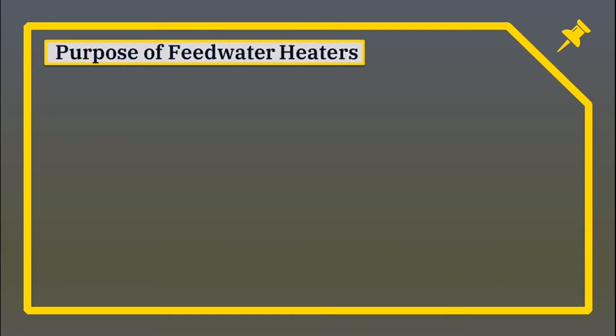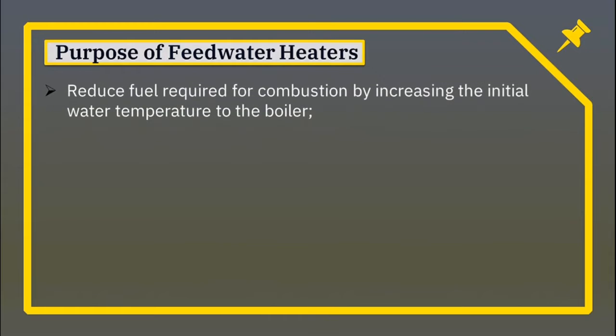Why use a feedwater heater? What is the importance? Feedwater heaters serve a number of purposes, all of which provide significant cost savings and environmental advantages. First is to reduce fuel required for combustion by increasing the initial water temperature to the boiler.